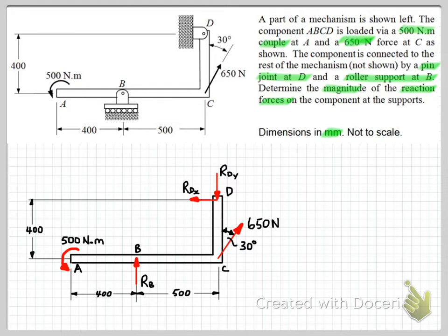And now that we've used component forces in X and Y directions, we should of course indicate what they are with respect to a coordinate system. Okay, so I've indicated over here the X direction, positive to the right, Y direction, positive upwards, and also indicated the positive direction for moments being anti-clockwise.